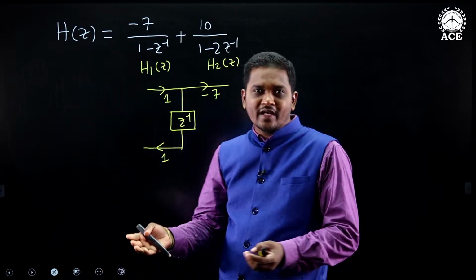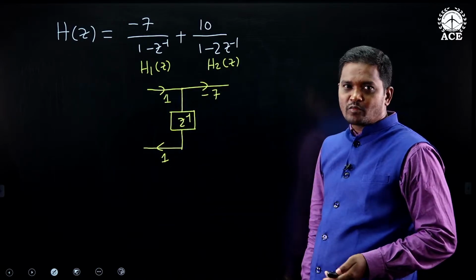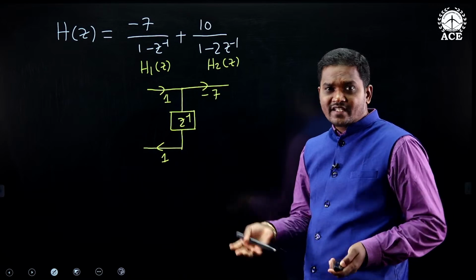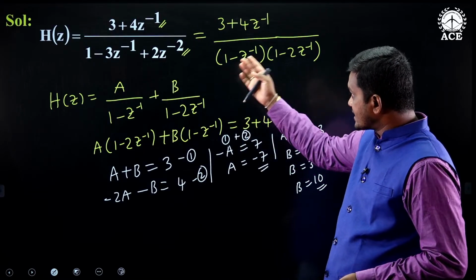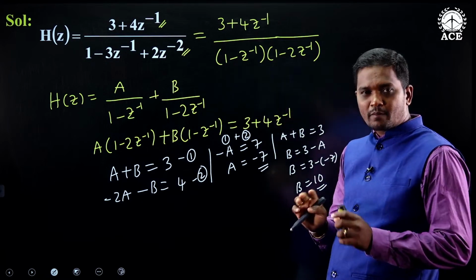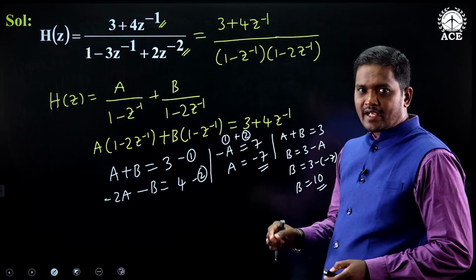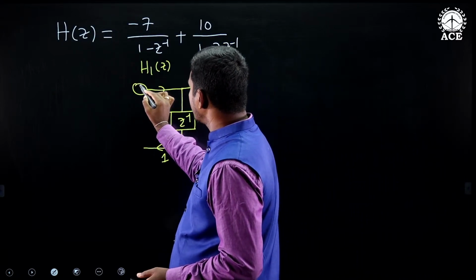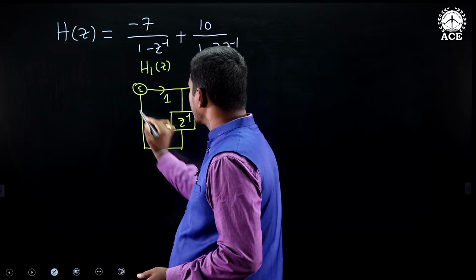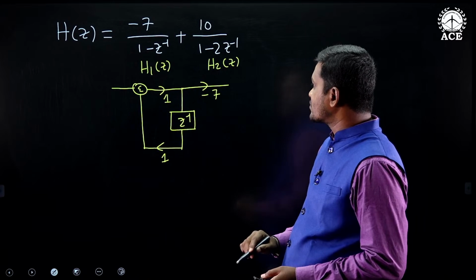I am doing it by the shortcut only now. This is the shortcut. I am implementing direct form 2 by using the shortcut. Other than this, the shortcut is not available, because you need to convert this second order polynomial to first order polynomial compulsorily. Only after that do the realization. Yeah, add these two. This first part is over. This is H1 of Z.